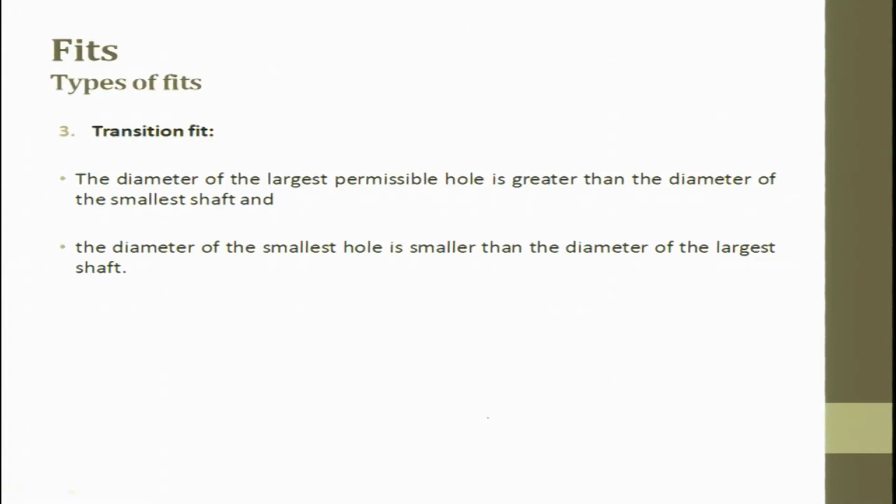Interference fit has lot of applications. Interference fit will not allow you to dismantle frequently. Clearance fit, yes, whenever you want, you dismantle. But here, once pressed, tightly held, it will be held. So, that is interference fit. We have seen the drawing for interference fit. So, let us move to transition fit.